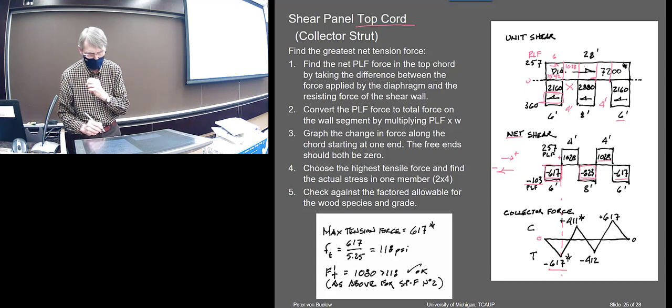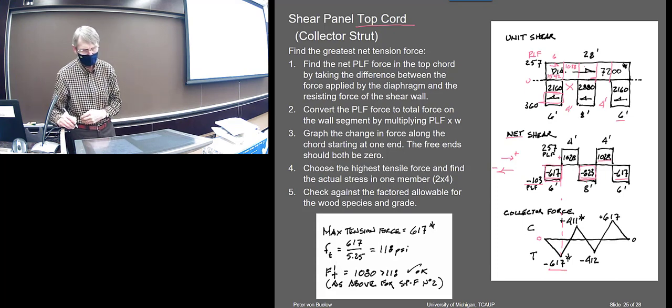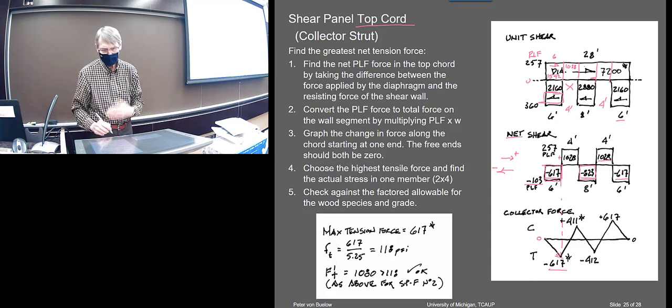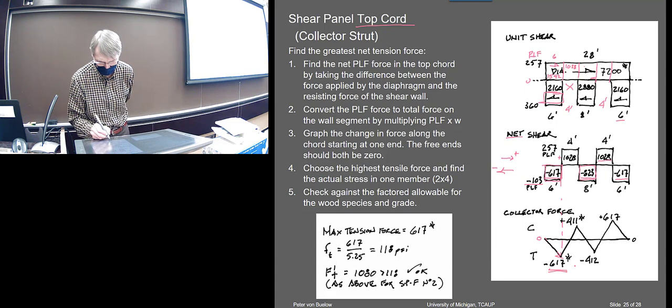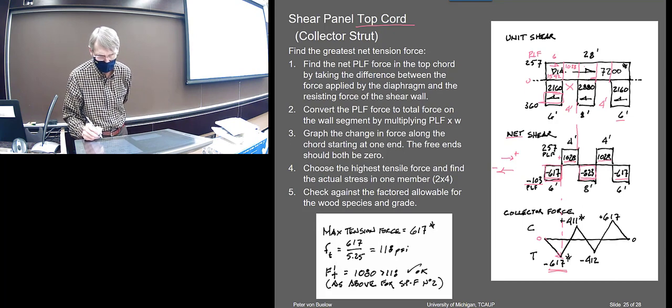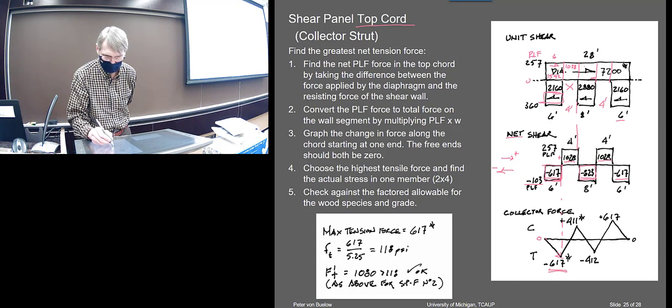The total for that width was 617, but it'll be a linear increase until you get to that 617. Then you've got to go from there up to the next point, this one, right? And across that point, it has a constant 1028. I mean, the total force is 1028. So you'll take the 617, or 1028 minus 617, and it'll give you a positive 411.